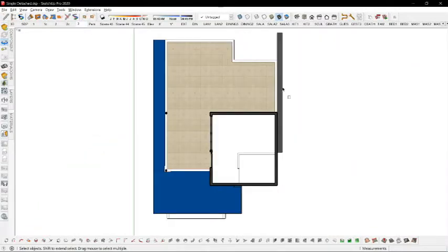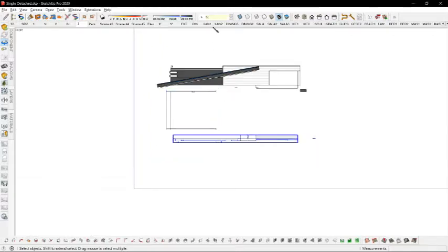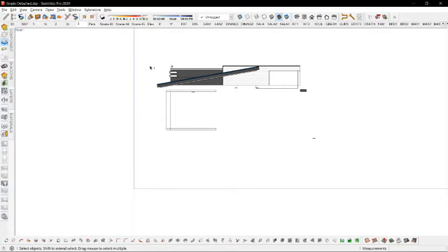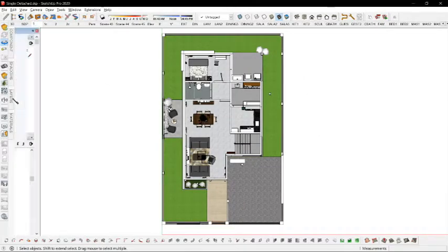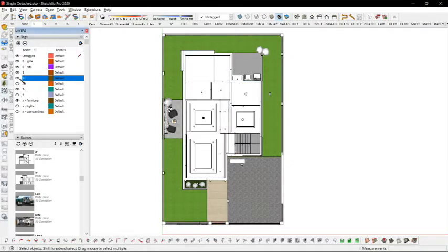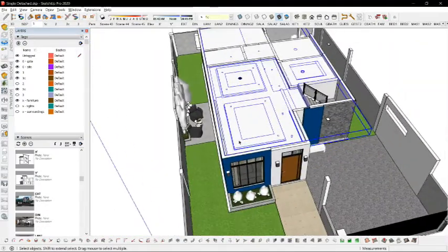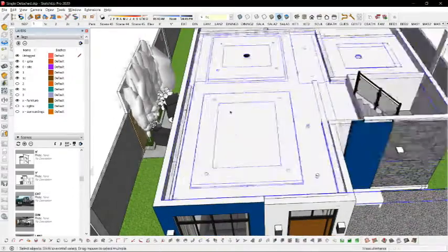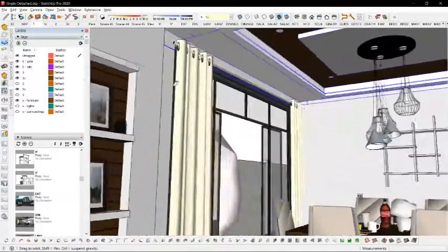3 for third floor. Ceiling, this belongs to 1C, which is first floor ceiling. Why did I place a ceiling layer? Because for example, we're working on the first floor and the ceiling is on, it will be hard to model. See, like you have to keep H to hide and then Shift H to unhide, or to move it so you could model again, or to use the section cut, but then you can't model properly.